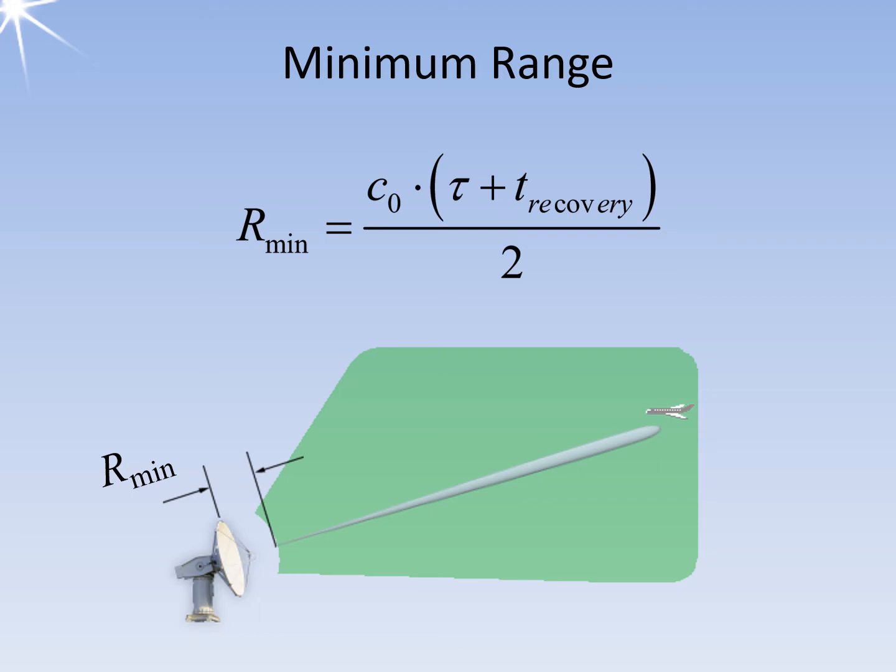Sometimes, this limitation is omitted if the radar uses only low transmit powers and then uses a ferrite circulator as a duplexer. This is also true for active phased array antennas because, although a large total transmit power is generated, the individual active antenna elements each apply a small portion of the power only.